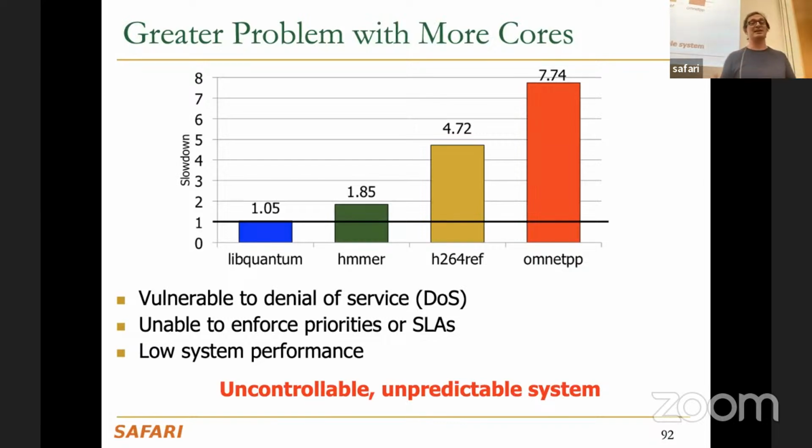It could be that system level control may be lost, because maybe at the system level, I really want this particular video encoding application to get priority, right? But I cannot enforce that because I have no way of communicating to the memory controller saying that you prioritize this thing. And you also get low system performance because your system doesn't progress very well. Meaning this core makes some progress, maybe, but it's very intensive in memory, so it's slow progress. The other cores may not make a lot of progress, right? In fact, if you prioritize some of these less intensive cores, maybe they're going to make much better progress, right? So basically, this is really bad for overall system performance, or throughput, as well.